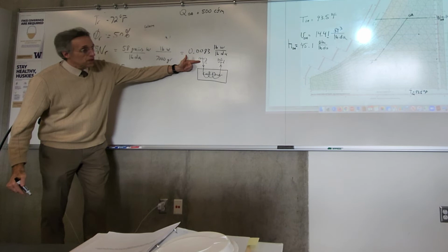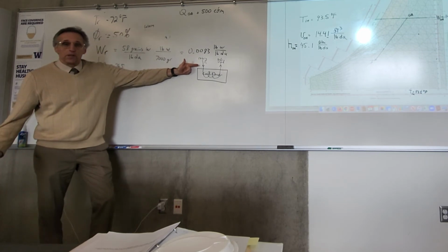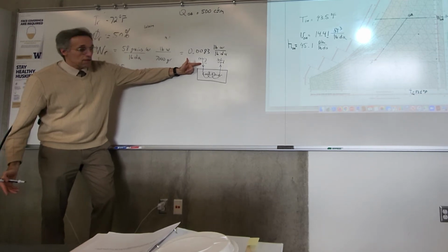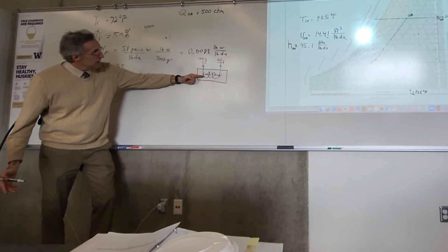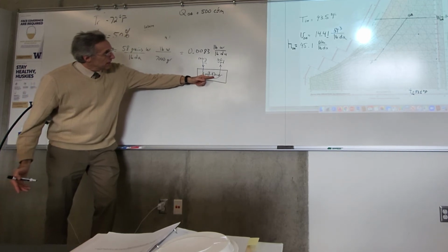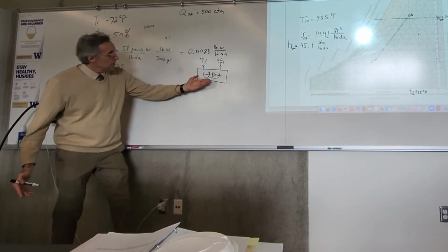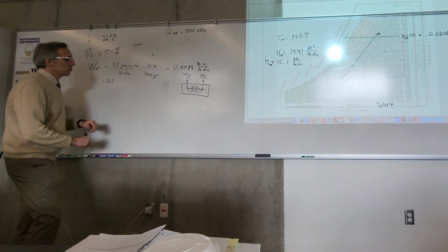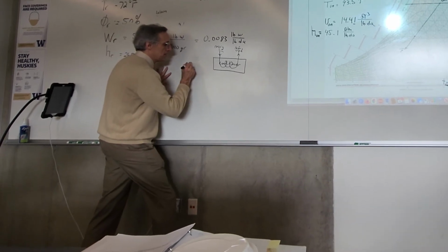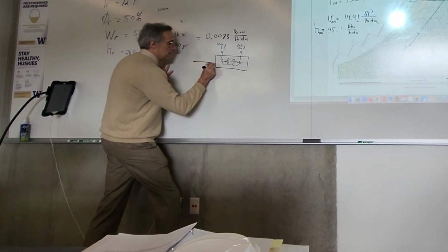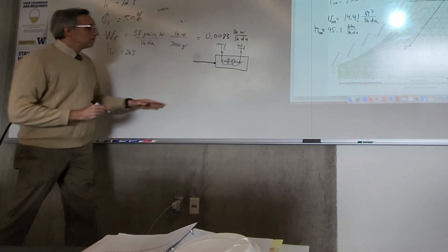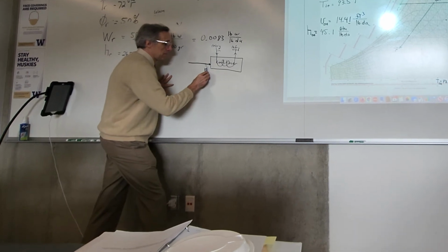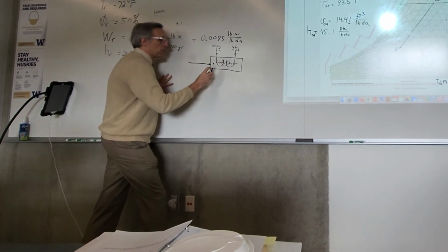We have a refrigerant coming in as a saturated mixture, coming off the throttling valve. It's cold, and its quality is about 0.3. It's going to go around and acquire the warmth from the air, and come out as a saturated vapor. We'll look at the refrigerant side a little bit later, but now we're just interested in QL, the heat that's going out of the air and into the low temperature reservoir, which would be the refrigerant.